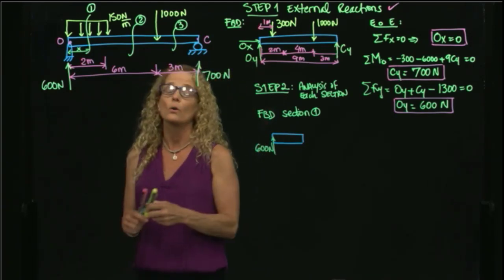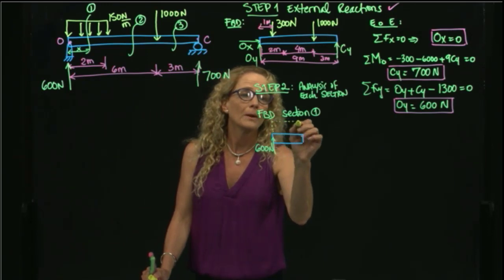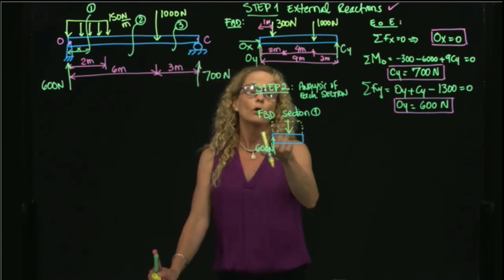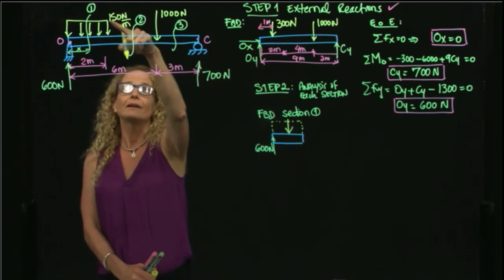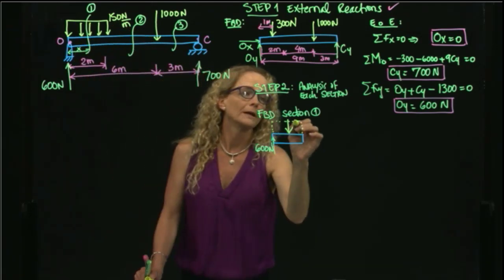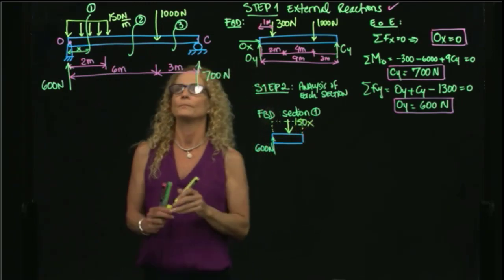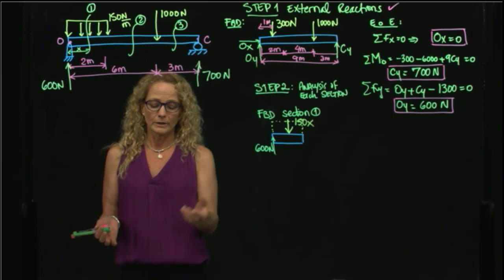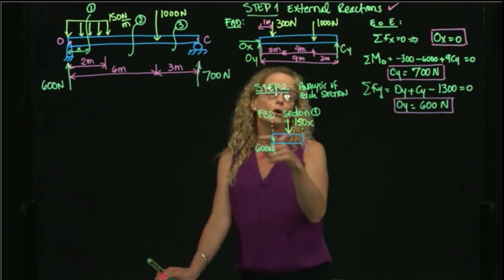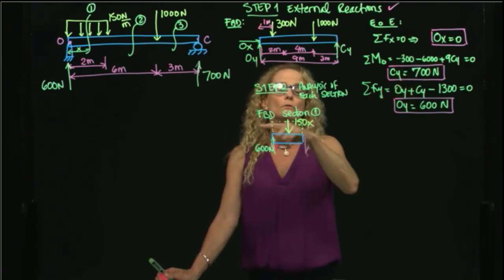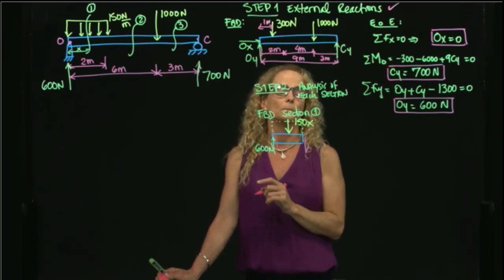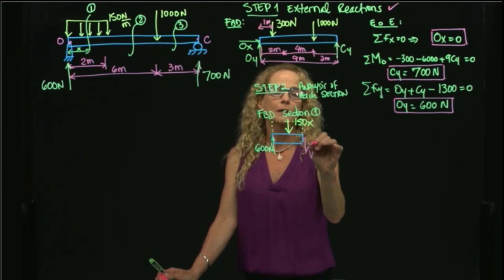That distributed load is a constant load, but what I will do is make a concentrated load an equivalent only for that section. Since this is 150, I will multiply by x, so it will be the height by the base, so it will be 150x. And I don't have any other force, I only have the internal force. As I say, I'm not going to do the analysis of the normal force, because we got that the normal force for the reactions is 0, therefore all the internal forces will be 0. So I have the shear force and I have the moment.